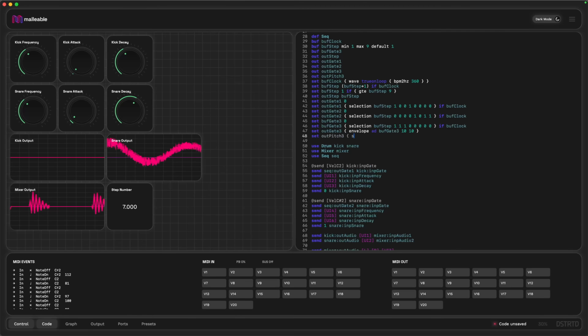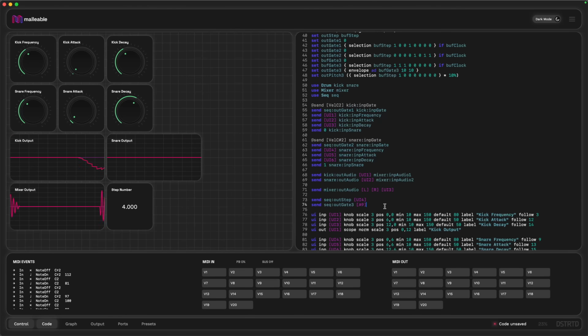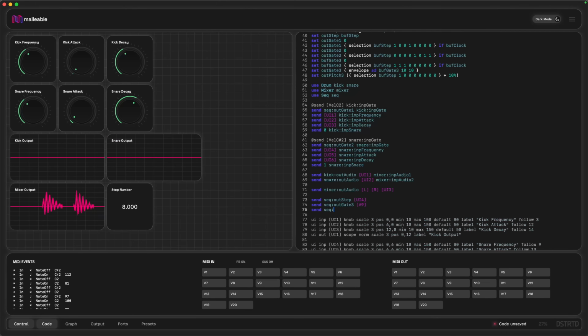using a selection function, which will use the buff step to determine which of these values it selects. But I'm going to multiply the output of that selection function by 10%, which will allow me to type in something like 1 for 10% and 2 for 20%, etc. Let me send that to the output on my Board Brain, and it's going to go to audio output 10, but it's going to be the calibrated audio output 10 to ensure that the voltage is correct.